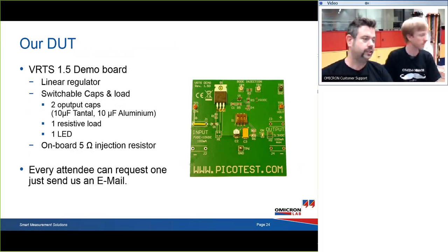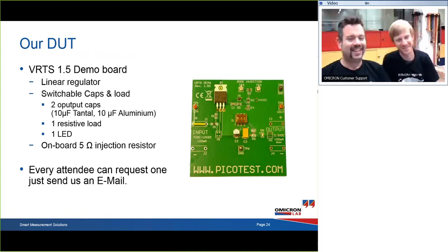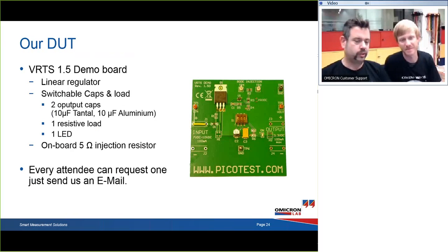So this leads us already to some measurements. Our device under test is the VRTS 1.5 demo board that Steve designed for us. VRTS means voltage regulator test standards. It contains a linear regulator, two switchable capacitors and a load. One capacitor is a tantalum capacitor with a low ESR, and the other one is an aluminum capacitor with a high ESR.